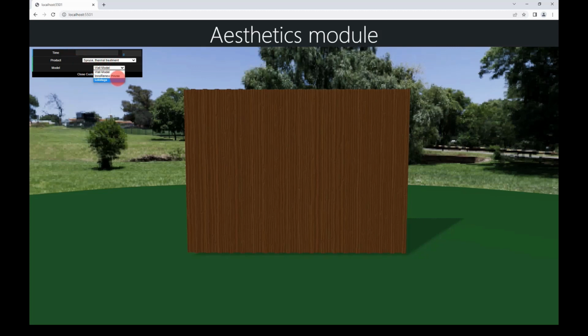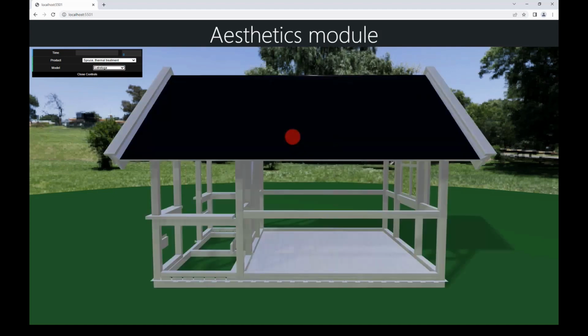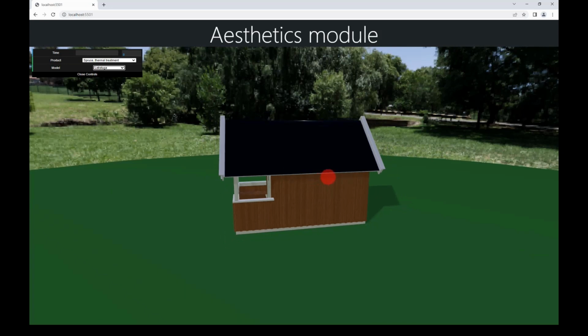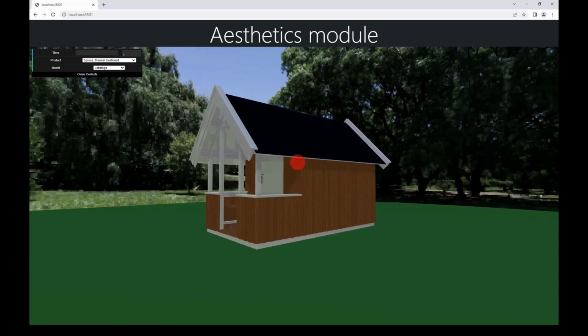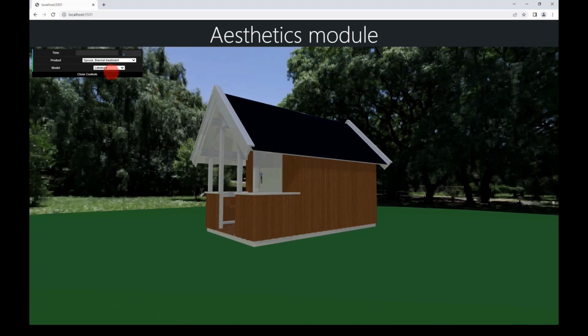So this is just a cladding. We might have a more complicated building. This is a playhouse I got from Swedish wood, just to test the concept on. So here you have some very deep eaves and some overhang protecting the decking. And if you do a CFD or environmental analysis here, you can see that the eaves will protect part of the cladding against driving rain. So these regions will not become weathered at all. And I'm sure you've seen this in some buildings with unpainted cladding and deep eaves.